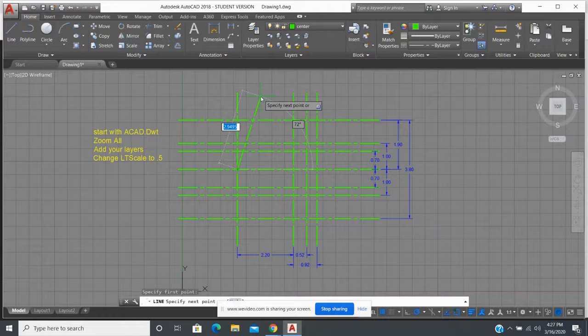I'm going to hit my tab key and jump over, and I can now change my angle. So I'll type in 60 here and hit enter. You always want to retype the number so that you don't end up with 60.3 or 60.8, or 59.2. It's going to round it to the closest number for us, and it could be slightly off.